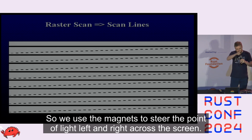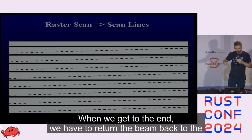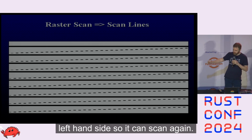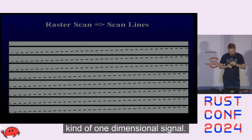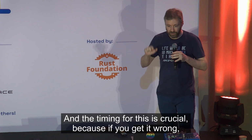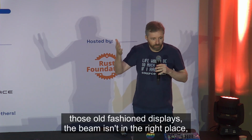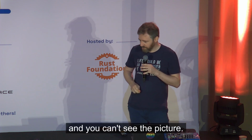So we use the magnets to steer the point of light left and right across the screen. When we get to the end, we have to return the beam back to the left-hand side so it can scan again. And so we're chopping up our two-dimensional display into this kind of one-dimensional signal. And the timing for this is crucial, because if you get it wrong, the beam isn't in the right place and you can't see the picture.